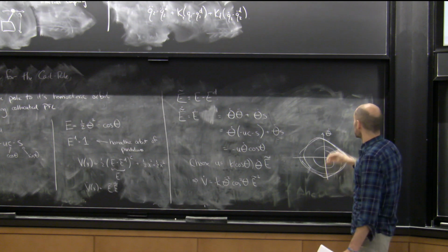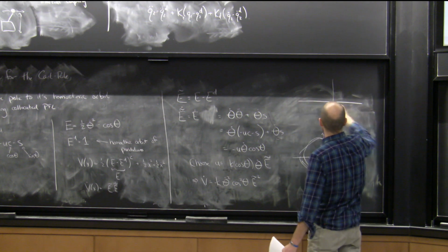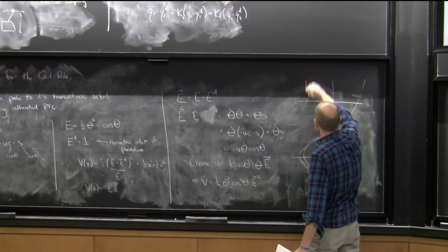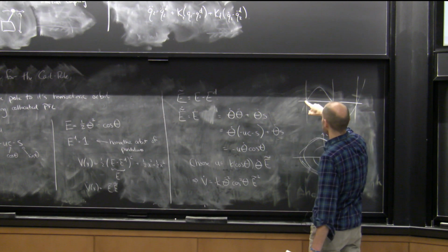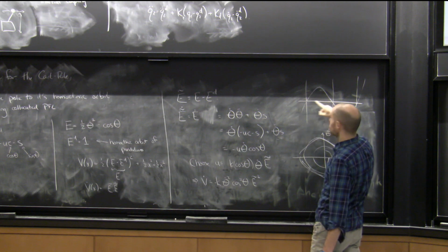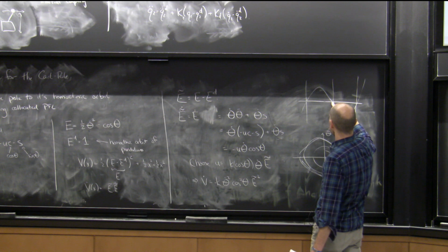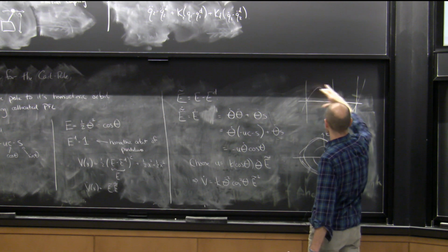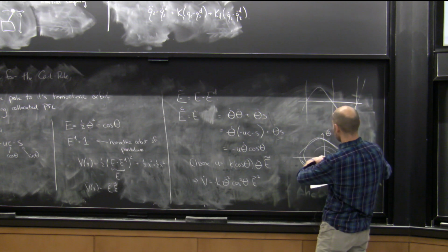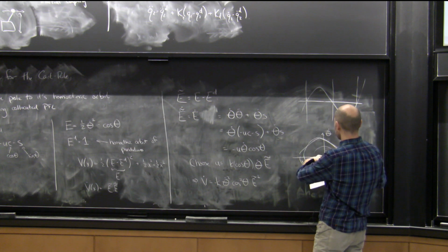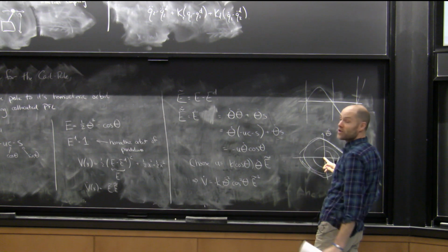In fact, V dot going downhill means I'm driving this way. And remember our region of attraction ideas here. Even in my simplest example, it was the same story. V dot was 0 here, V dot was negative inside here, V dot was 0 here. But by virtue of being inside this bracket, I could estimate the region of attraction of this fixed point. And for the pendulum controller, it is actually the whole state space except for the origin.